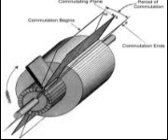Figure 9-11. A field coil removed from a field pole. Flanges fitted with bolts. Rings of mica insulate the segments from the flanges. The raised portion of each segment is called a riser, and the leads from the armature coils are soldered to the risers. When the segments have no risers, the leads are soldered to short slits in the ends of the segments. The brushes ride on the surface of the commutator, forming the electrical contact between the armature coils and the